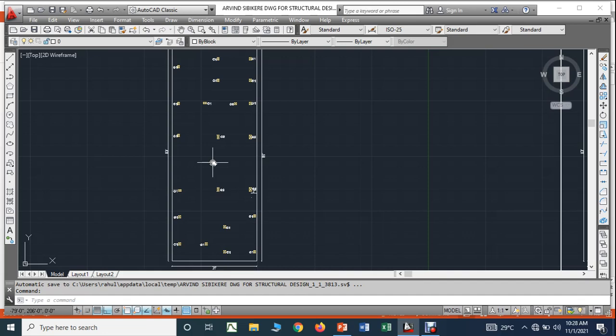But after analysis, as a structural engineer, you have the freedom to reduce the number of columns, because as a structural engineer it is our duty to optimize the design and make the design safe also. Both the things should be there. Therefore as an engineer you have the option to reduce the number of columns also, or sometimes because of the very unusual designs in the plan, you may need additional columns also. So therefore you have the freedom to have additional columns and beams also without altering any client's requirement. That is most important, without altering any client's requirement.